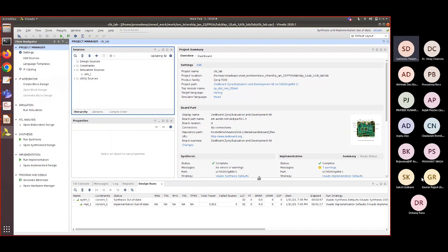Is shift register LUT only for SISO or any other operation? You can use it only for SISO. We cannot change it into PIPO, because there is no parallel load facility. Only for SISO operation, because it has restrictions, right?